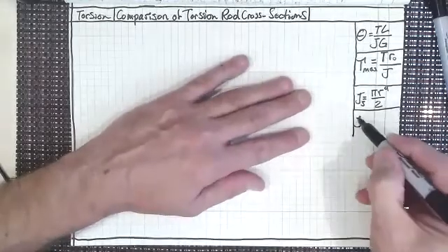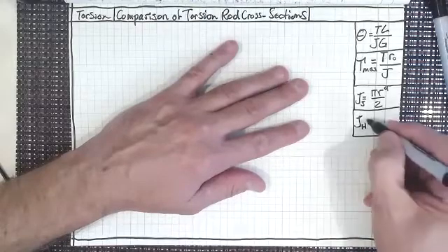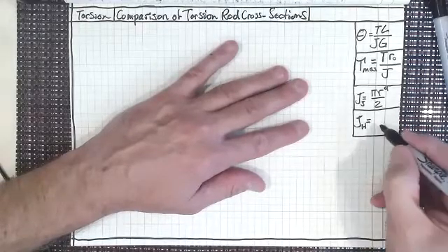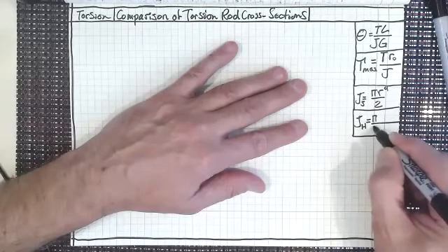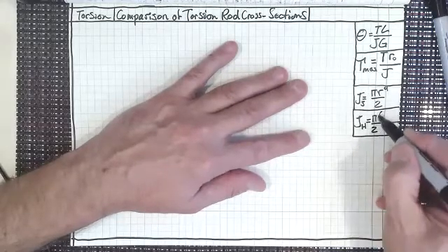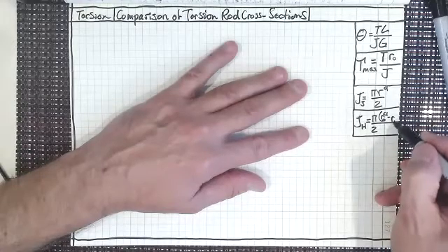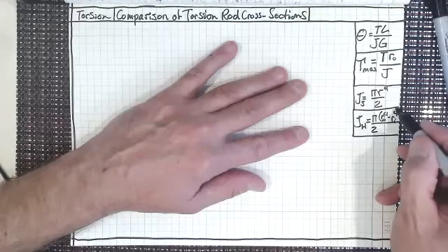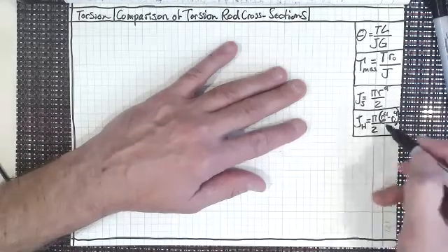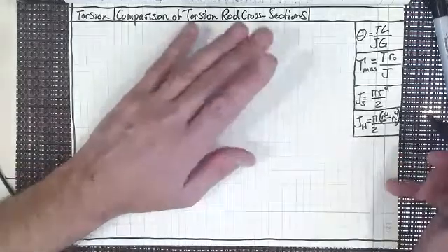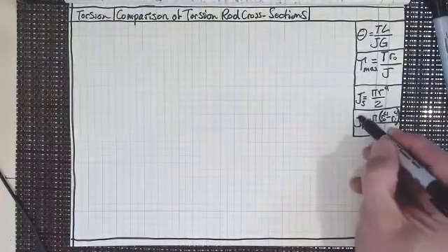Now, when we say a hollow cross section, where's the line there that we cross over? Well, that is still going to be pi over 2, but now it's the outer radius to the fourth minus the inner radius to the fourth. And you'll see that there's a difference here from the mass moments of inertia that we worked with, because this is a minus, which is what you would expect it to be. And that's for a hollow cylinder.